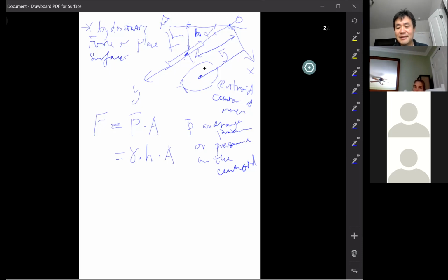Okay. This is some geometry. If you're not familiar with this, spend some time after class to look at those geometries. In appendix figure A1, it clearly shows the center. So if there's an inclined semicircle under the water, you need to find where exactly the center is in order to find exactly the water depth on top of the center.